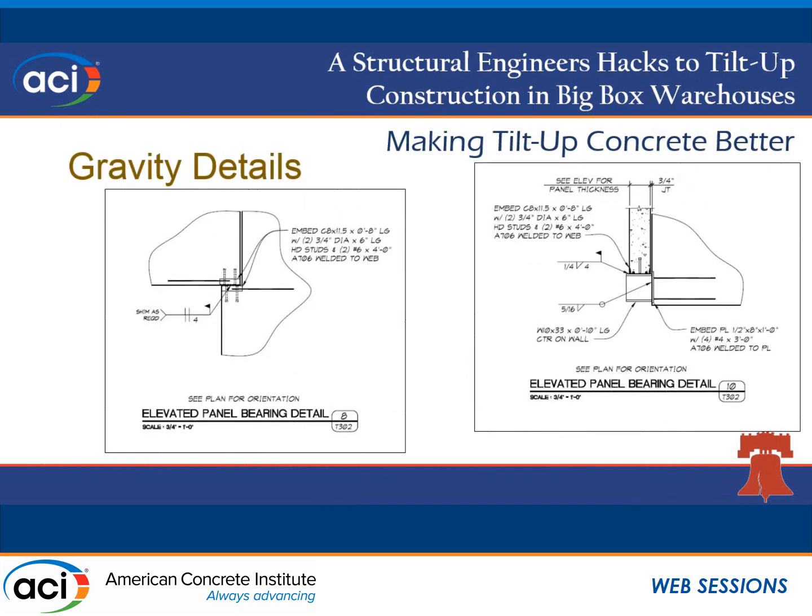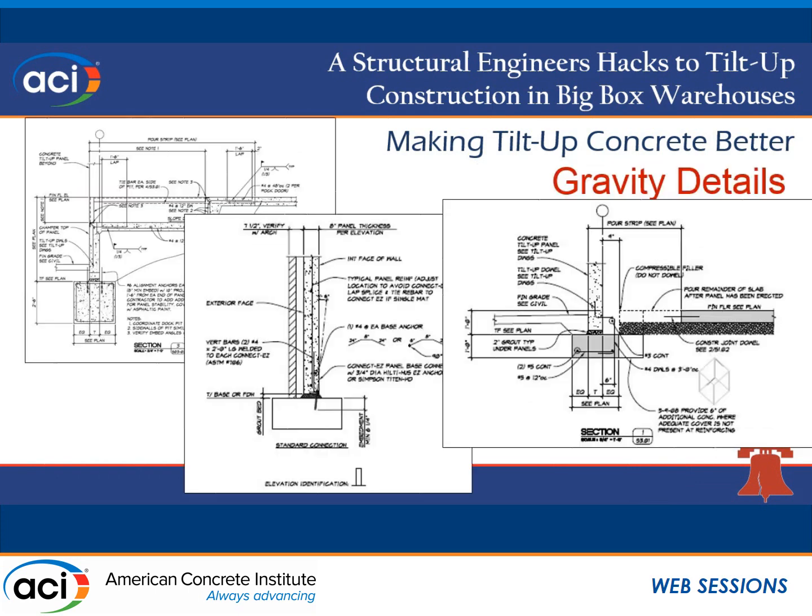They love to put channels on the wall. Bearing type connections. Again, there's my W12 seat. I hate stiffened angles, so a W12 does the same work. Base connections. You've got your typical loading dock. You've got a veneer panel showing the Connect EZ. And you've got kind of your typical cast-in detail.